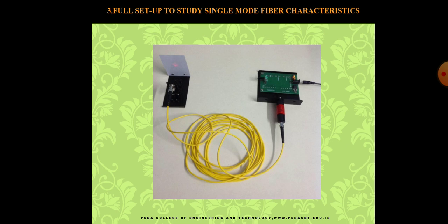The pattern on the screen may be varied by gently distorting the cable in the midsection to change the path length of the light propagating through the core. This has to be done carefully without disturbing the power coupling. The spot on the screen will be more distinct if the lights are dimmed in the laboratory.